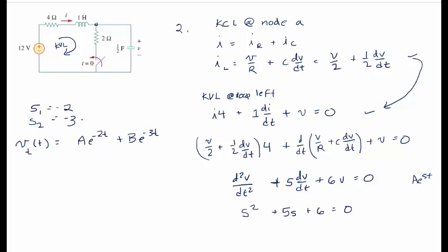If they were equal roots, we would know that it is a critically damped solution. If they're unequal roots but real, we know that it's an overdamped situation. And if they were two complex roots, you would know that we had an underdamped solution. The A and B, or the A1, A2 as the textbook previously called them, are to be determined from the initial conditions.